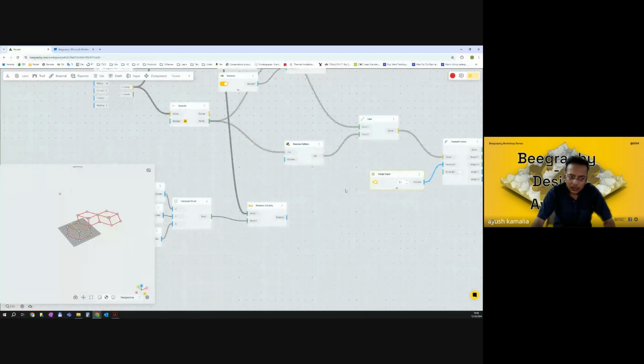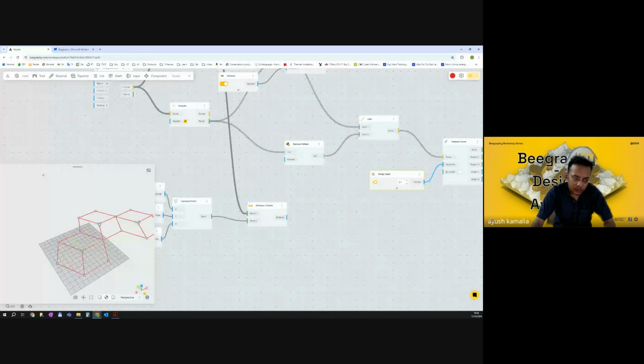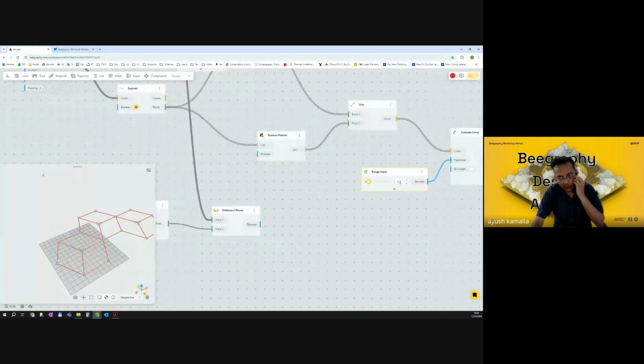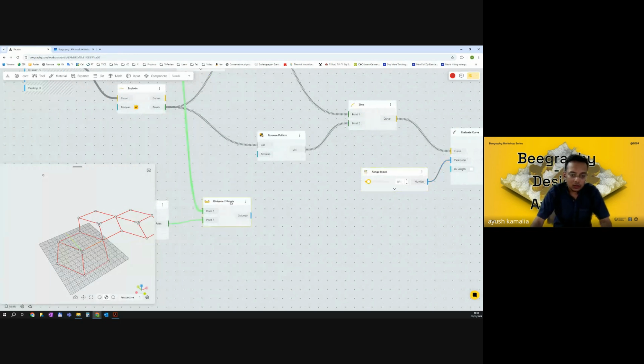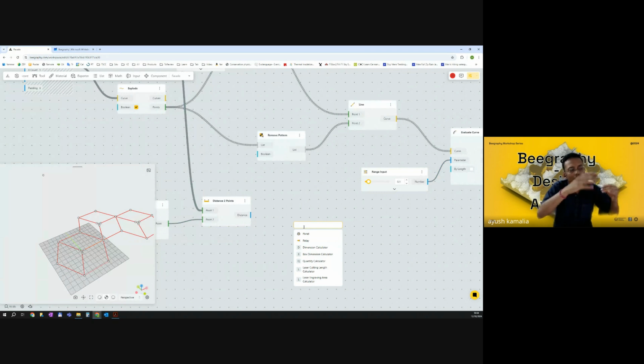But we just realized that the parameter that we want to input to control the position of these points in the hexagon should be between 0 and 1. So what we can do is we can remap these numbers. Remapping means taking a range and keeping the same sequential distribution, but applying the same values into a different range. In our case, the range will be 0 to 1, but we decided that physically it is impossible that the panels are 100% open, so we can have the range between 0.05 to 1. Okay, then let's just remap the numbers.